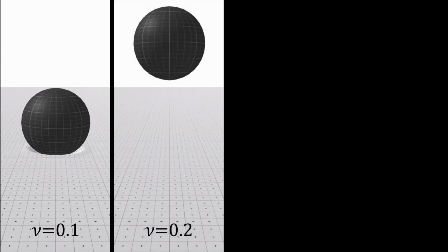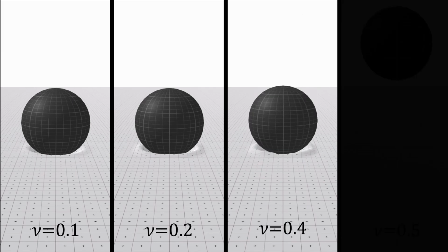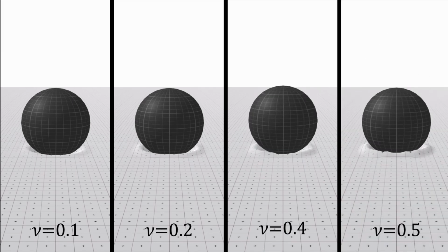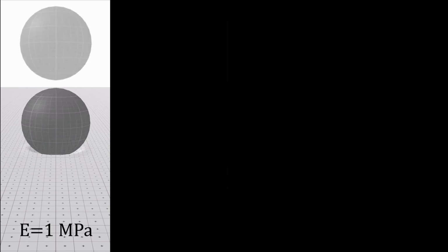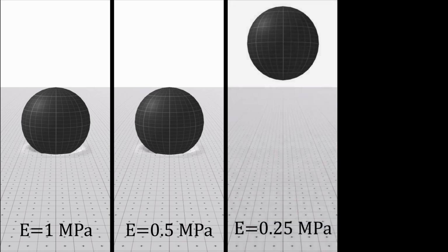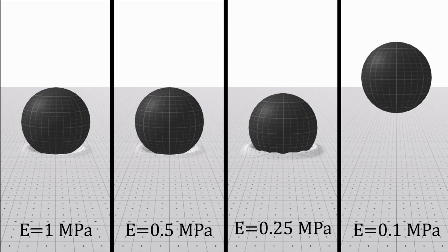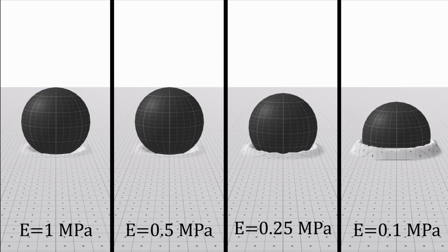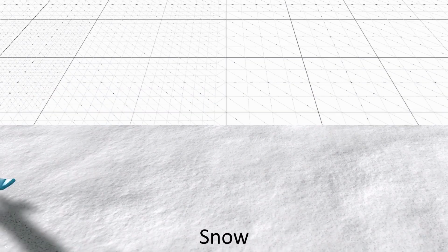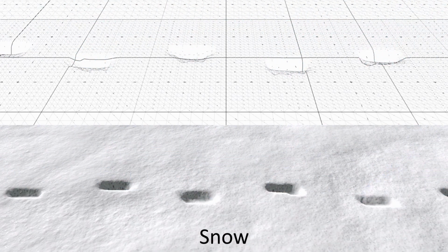For a real-time deformation, we introduce a plastic model for terrain compression. Such a model takes the previously calculated time-varying force that the character exerts on the ground and estimates a pressure using a linear stress-strain relationship, defined by the terrain characterization, which is based on parameters such as the Young modulus or the Poisson's ratio. Both the force model and terrain deformation can be used to characterize multiple types of terrains.